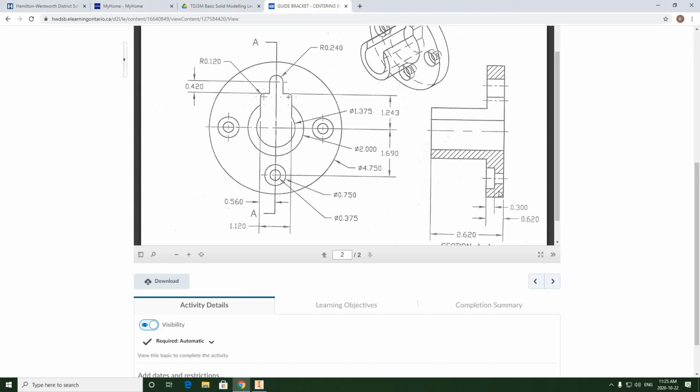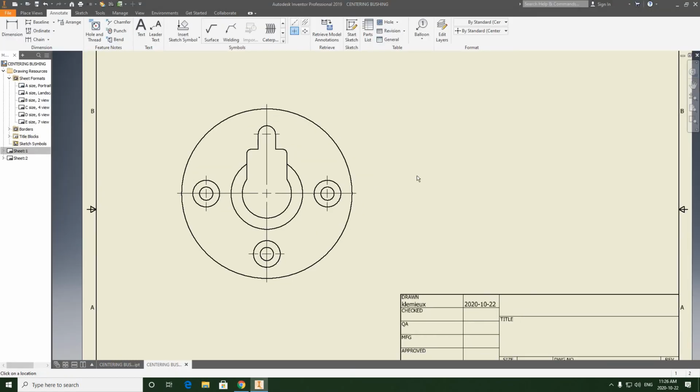So all these diagonal lines that you're seeing, this represents cutting marks, right? So we're imagining a saw coming down and cutting this right in half vertically top to bottom, and then wherever there's solid material that the saw passes through, it's projected in a sectional view with diagonal lines to represent saw marks, right? So it's a combination of the cutting saw passing through nothing and solid mass. So that's what we're seeing in a sectional view. So creating the sectional view is quite simple.